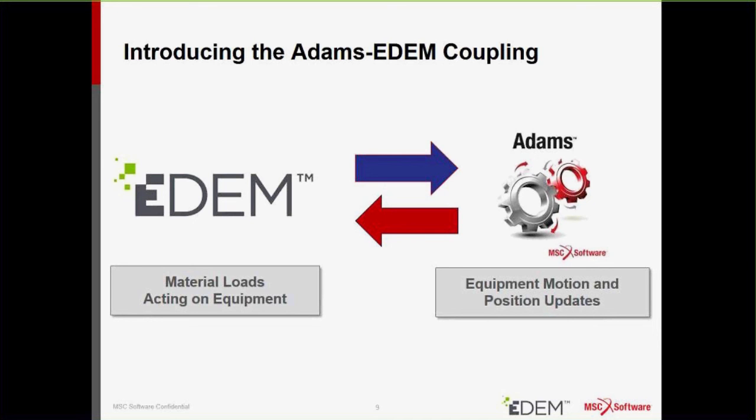The overall premise is pretty simple. So when you're performing a co-simulation using the coupling, both EDEM and Adams run simultaneously. And during processing, there is an exchange of data between the 2 software. On the EDEM side, we gather all the material load information that is acting on the equipment over time. This information is then passed to the Adams solver, which then uses the load data to understand what impact this will have on the equipment motion, and then provides an update to the position of each of the components.